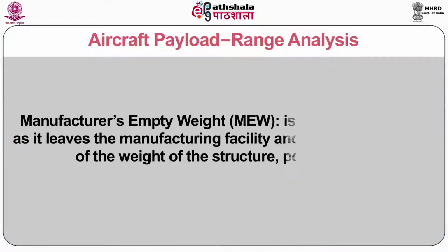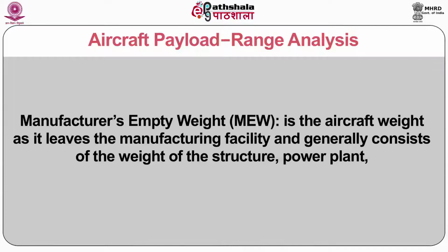Operator's empty weight, that is OEW, means the weight of the aircraft prepared for service and is basically the sum of the manufacturer's empty weight, that is MEW, standard items, that is SI, and operator's items, that is OI. Manufacturer's empty weight, that is MEW.